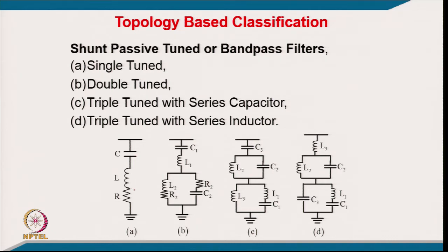So you have normally an L and C circuit which is tuned for a particular frequency, like maybe the third harmonic for single phase and maybe the lowest, fifth harmonic, in three phase, which can be sucked into this circuit. Because L and C are designed in such a manner for that particular harmonic, like the fifth harmonic, they cancel out the reactance of each other and suck the harmonic.